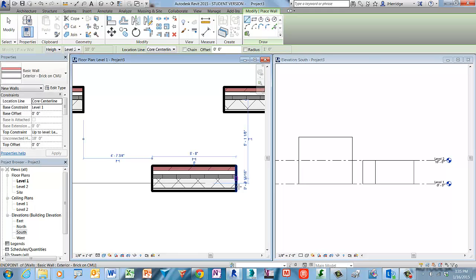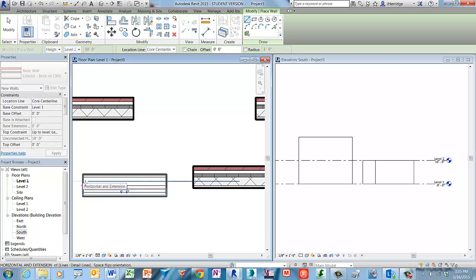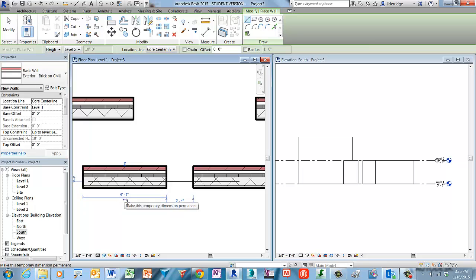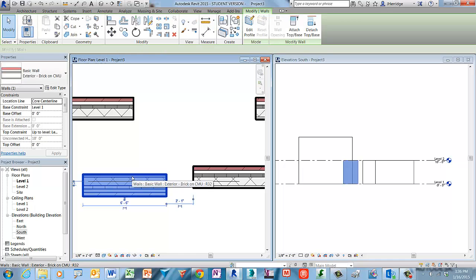So as I place the start point and the end point, note that the exterior face is facing the top of the screen. Now, if I place another wall instance, but this time going from right to left, using the same wall type, tracing over the same reference plane line, note that the exterior face is now pointing downwards on the screen. So I just wanted you to understand this directional behavior of layouts, but understand that if the desire was to have the exterior face go to the top of the screen, you can select these flip grips to change its orientation behavior.